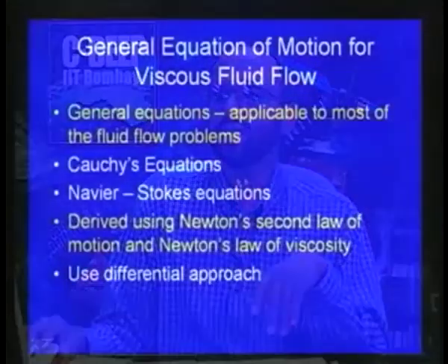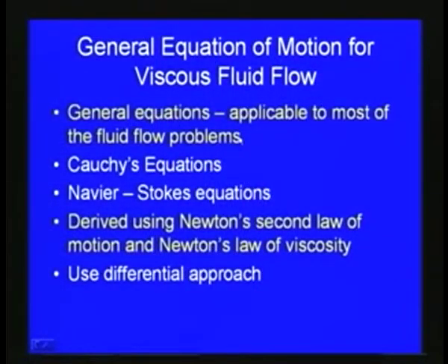So, our aim here is to derive the equations which are generally applicable to any kinds of problem, applicable to most of the fluid flow problems. First we will derive the Cauchy's equations. The Cauchy's equations are applicable for all kinds of problems, compressible, incompressible, or all varieties of fluid flow problems, and then, especially when we consider incompressible fluid flow, we will derive from the Cauchy's equations the Navier-Stokes equation.